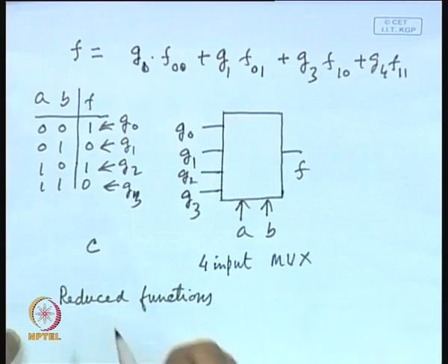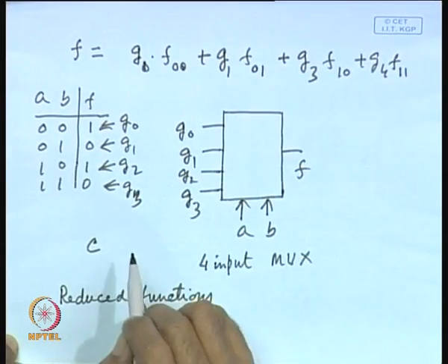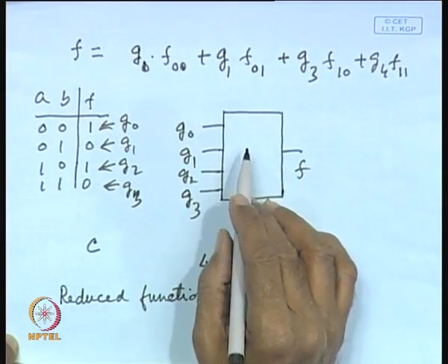That means, using pass transistor logic you can realize Boolean functions using multiplexer as the kind of building block, where the multiplexer is realized using pass transistors. So, this is how it can be done, and it can be proved that this is free from all the problems that I discussed. That means, all the design rules which I have mentioned are followed here. None of the 3 design rules that I have told is violated in this case.